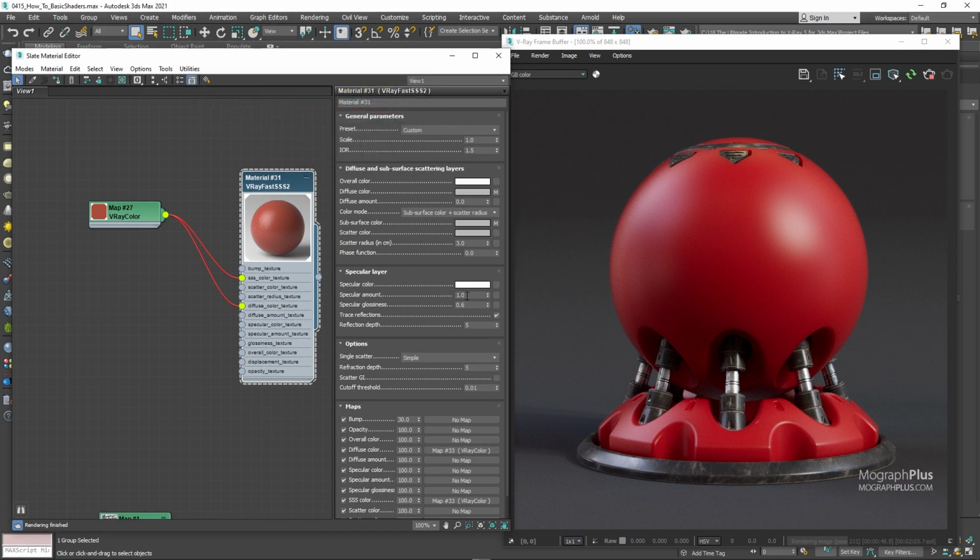It's called specular in the subsurface scattering material. And the IOR value for most daily shaders like plastic, wood, concrete, and so on can be around 1.5. The only thing we are interested in is the specular glossiness or roughness. We add variations to the specular glossiness with a grayscale texture, and that adds all the realism we need.